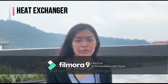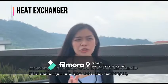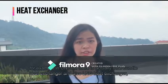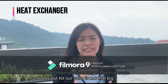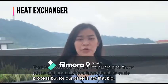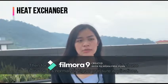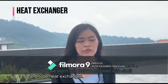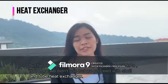For our case, we use the shell and tube heat exchanger and not other heat exchangers. For example, in UNISIM, there's actually a tube bundle heat exchanger and also an LNG heat exchanger. The LNG heat exchanger is normally much pricier and it's normally for a larger scale process, but our case is not that big. Then the tube bundle heat exchanger, we didn't use because it's normally for higher pressure applications. But for our case, we just use a pressure of 100 kPa, therefore we proceed with the shell and tube heat exchanger.